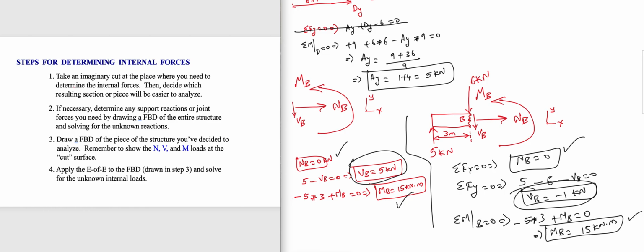And these are the steps. You have to make an imaginary cut at the place where you need to determine the internal forces. And you have to decide which section or piece will be easier to analyze.